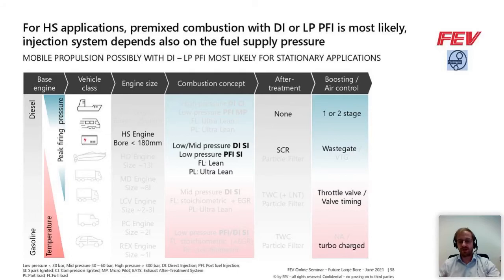And there we can already see that the boosting system will be one of the major challenges or major points of differentiation, as the richer relative fuel-air ratios are our limit basically regarding pre-ignition and knock, and therefore this is also determining somehow our load range that we can achieve. After treatment for many applications can be done without a system, but for the most stringent ones, an SCR system will be necessary.